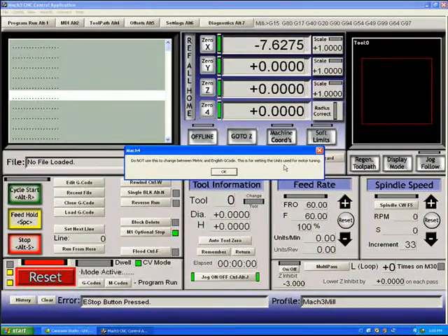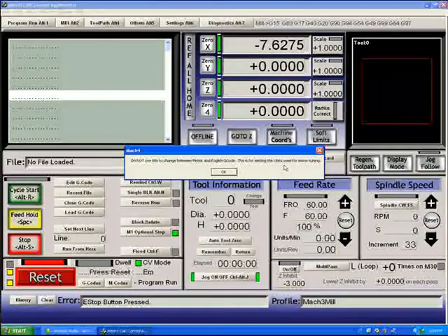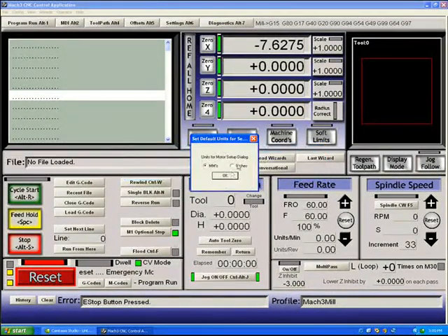You will never use this setting again. Once you set it, leave it alone and never change it. There are other ways to switch between English and metric for your G-code programs. If you change this setting, once you've set it, you'll have to retune your entire system. So pick a common use of your system and use that.